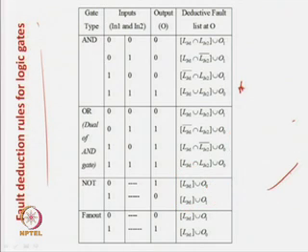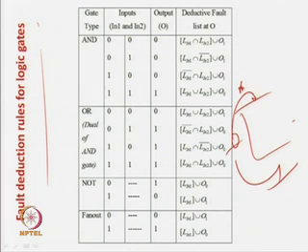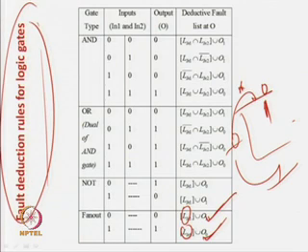So, we have seen the fault gate. Whatever the list is here will be propagated here and here. And if you get the value 0, a stuck-at-1 is detected, and if you get the value 1, a stuck-at-0 is detected. This is just the reverse. So, if you get the signal value 0, a stuck-at-1 fault is detected. If the signal value is 1, a stuck-at-0 fault is detected. So, this is actually the fault detection table for the fault list.